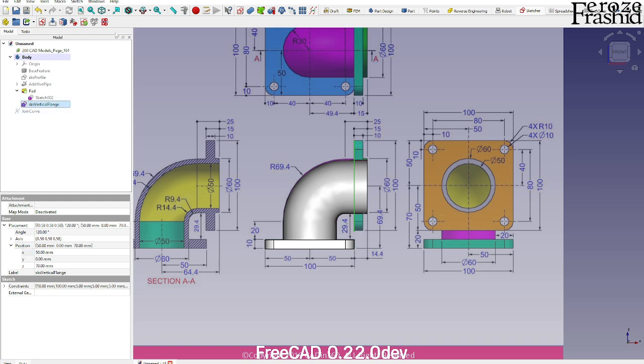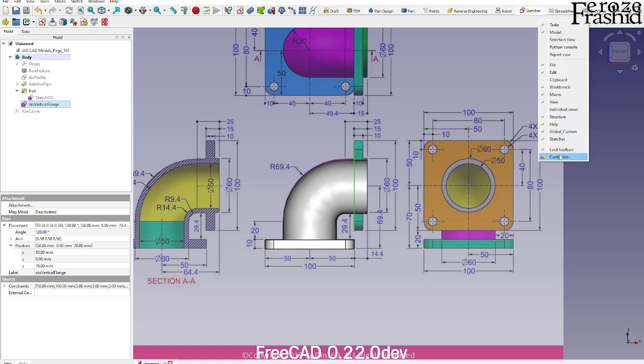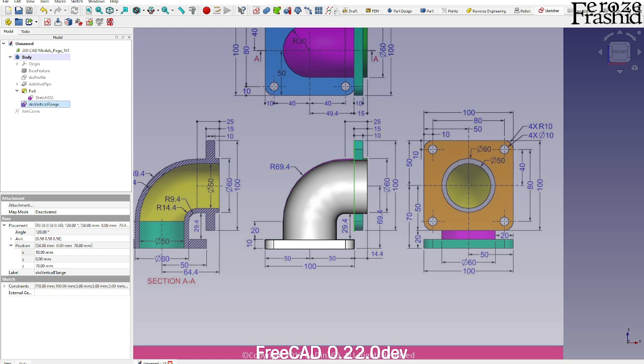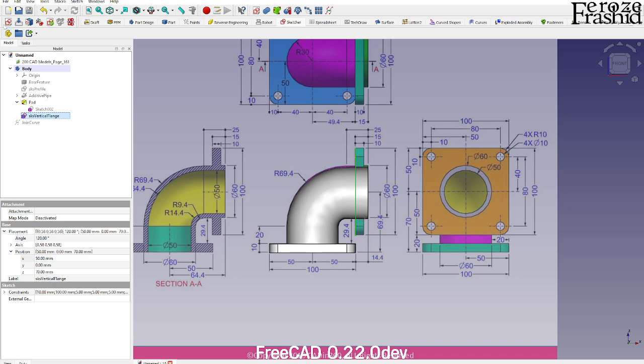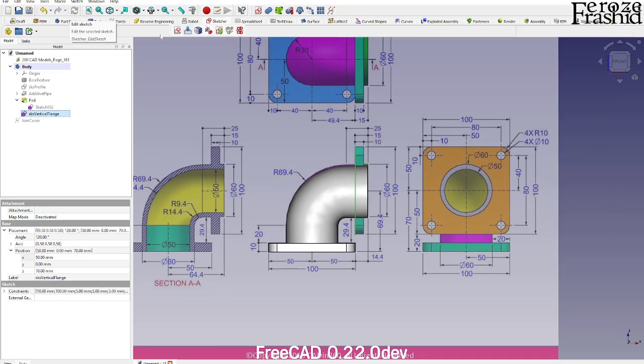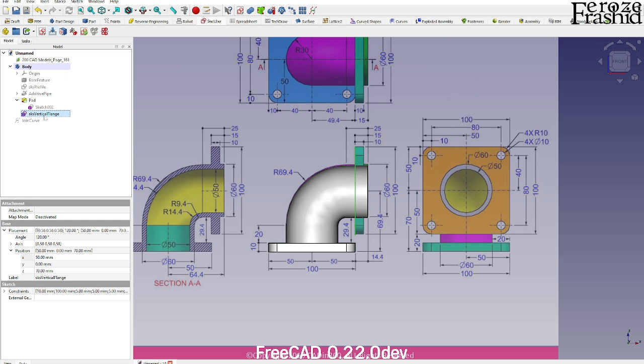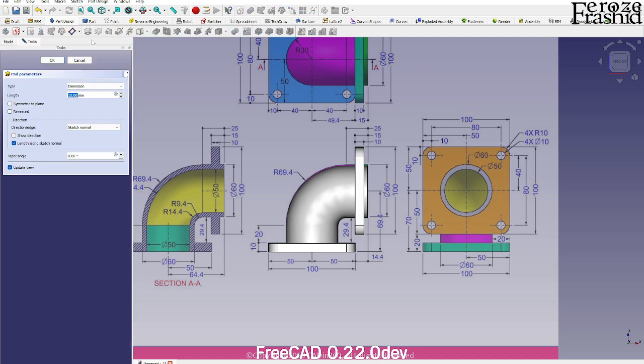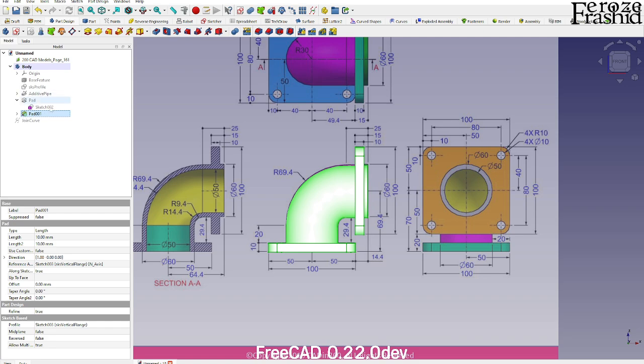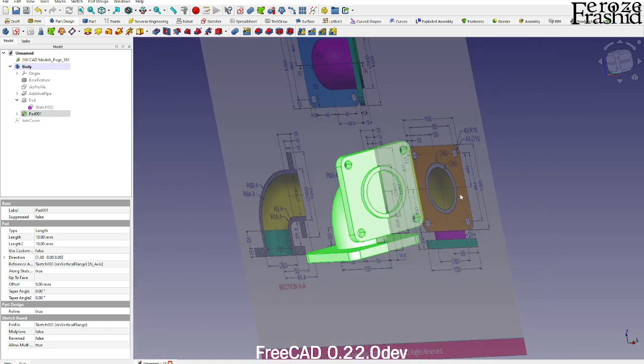Now I can go ahead and make another pad. I don't know why it is there. I prefer it to be down here and this down there. This is my global. Nope. Yeah, this is much better. Okay, now I can go ahead and go to our design, select this sketch and make a pad of 10 millimeters. So it's going forward. We're good with that. And what it does is, in Part Design, the Boolean operation is by default.